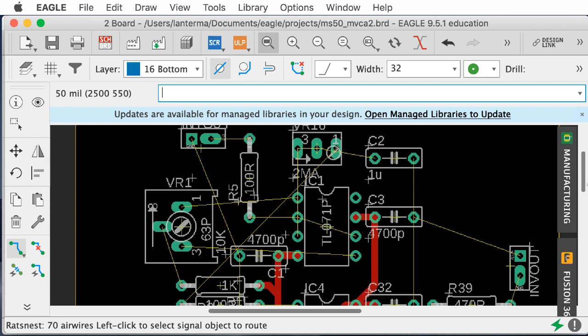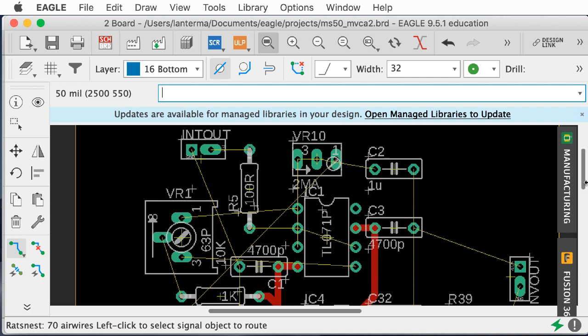Is it acting as an antenna? What about the low impedance? Well, of course, then people say, well, a chassis on something like a tube amp, that's like a giant ground plane. I'm just going to go with a couple of ideas. One is I generally don't see people use ground planes on audio circuits, whatever the reason. So I stick with that.